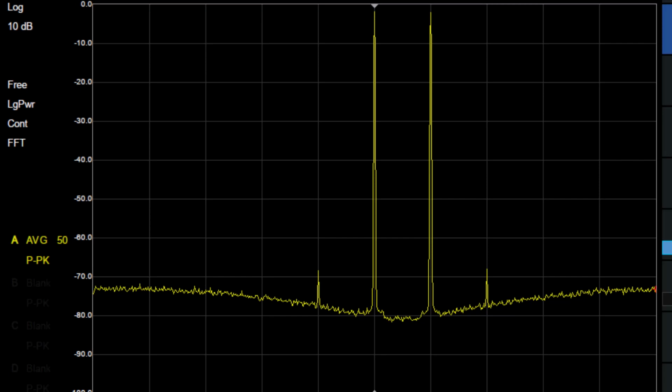The next question asks, what transmitter performance parameter does a two-tone test analyze? What it's designed to do is test linearity. That's the answer. A perfectly linear transmitter is going to produce those two tones and only those two tones. So if I input two non-harmonically related tones into the transmitter, it's going to transmit only those two tones.